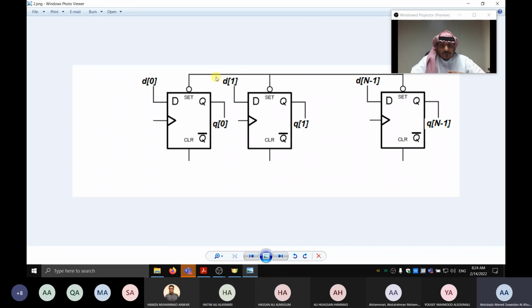No, to 1. Yes, so I need to connect it to 1. 1 means disable. You see, it's inverted, so you have to be careful. So I need to connect it to 1, which means the power source, the voltage, like 5 volt or 3.3 volt. It depends on the system. You just connect it and relax.